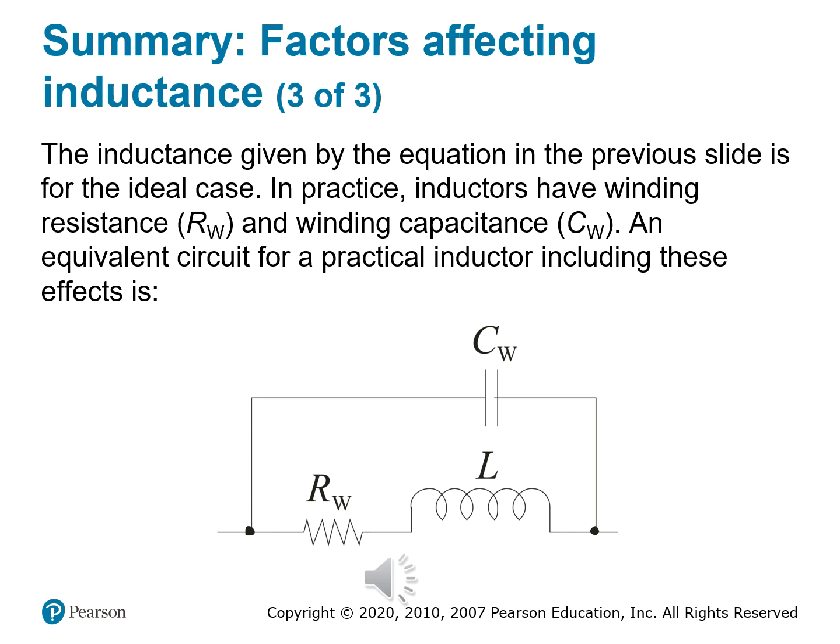And again, one little bit of foresight with C sub W. A major problem that we have in critical equipment that's sensitive to interference is called leakage current. So in medical devices, if you hook up a patient to a medical device and there's a conductor actually making contact with the patient, you're forming the basis of what a capacitor is, and you get stray current leaking across that gap. And so we have to keep track of these things so that we don't actually electrocute patients.